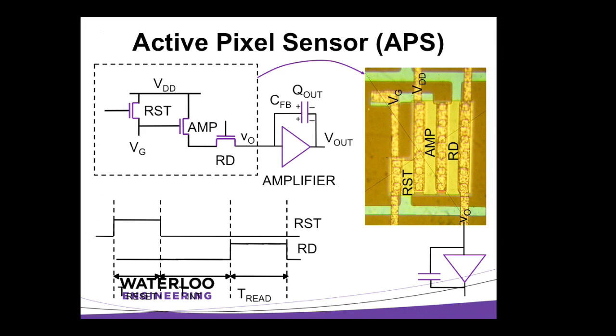The problem with voltage mode was the resistance associated with each of the switches, the RC time constants were too long. So anytime you tried to build anything that would respond in a reasonable amount of time, it would take forever. But when you switch to current mode, you get rid of that problem. So we actually introduced the first class of circuits for amorphous materials, current mode circuits, and they became the de facto way of making circuits in amorphous materials. In fact, OLED drivers were using current mode circuits as well shortly after we did this work with active pixels.